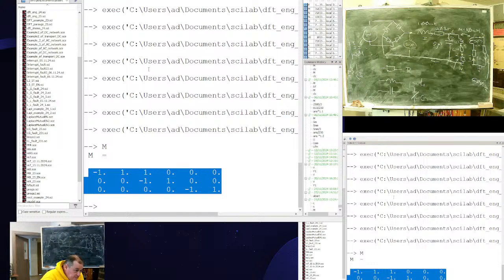At third harmonic it triples, and the capacitor's reactance will be 1/3, and so on. From this point I will get the matrix of resistance for each harmonic in AC mode. Next, a vector. It's a vector of EMF. I have EMF only in the third branch.